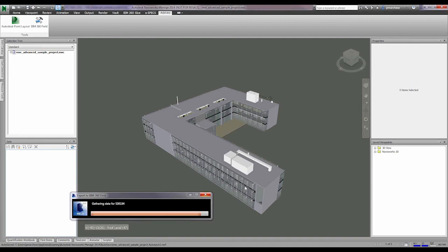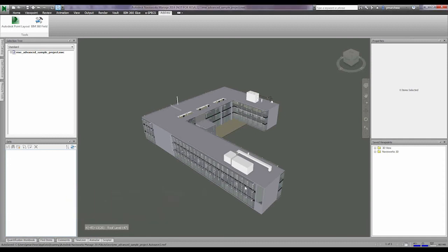Now you might say, well, yeah, but we're sending things into Navisworks from Revit anyway. Shouldn't the categories be there? That's true. But because Navisworks could use information from a multitude of different programs, you could have things in there from Revit, AutoCAD, Civil 3D, MicroStation, Vectorworks, SketchUp. So categories don't coordinate between all of them. But if I create a search set or selection set, that's something that's consistent. So the data could be coming from 5 different things,